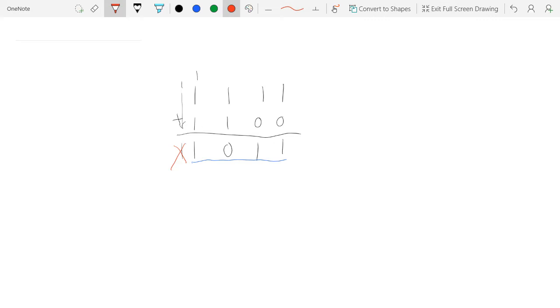But the CPU doesn't necessarily know that. It doesn't necessarily know, well, hey, I had 4 bits coming in here, and my answer was 5 bits. That's 1 bit too many. It doesn't know that. It can't count how many bits. How it knows whether there's an overflow or not is it looks at this last bit here, and it sees that it's 1. So this last bit here is our overflow bit. And it'll make sense in a second how this ties into the circuitry. But we essentially want to look at this. If it's 0, it's alright. If it's 1, it's an overflow.